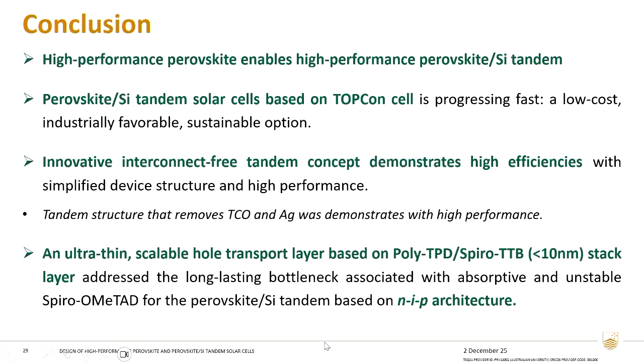And that's for the scalability, and the second is the stability. The best outdoor stability of the perovskite silicon tandems has been tested for 1 year with an initial efficiency of just around 21%, with 20% efficiency loss over 1 year of outdoor stability testing. So that's a significant efficiency drop. The initial efficiency is far away from what we require for a commercial product, and the degradation rate is also much faster than what we need for commercial products. So we still have a lot of things to do, a long way to go.